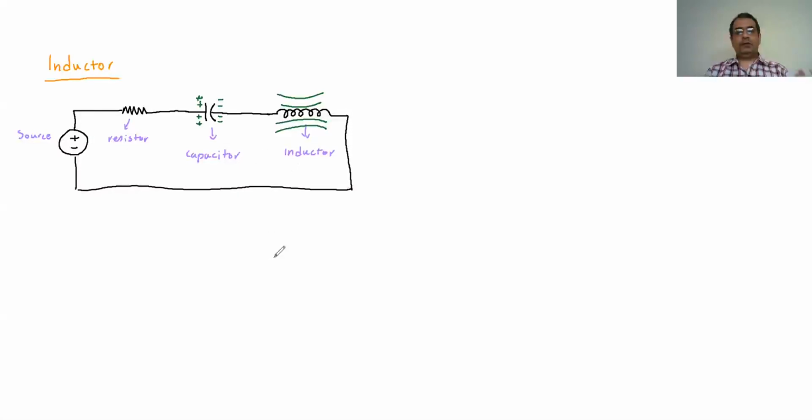So remember that whenever you work with the elements in a circuit, you may disconnect the source. You look at your circuit and see there's no battery connected, or it's not connected to any source of energy. But still, these two might hold the energy. So if you touch it, you're going to get shocked, because although they might not be connected to the source, they store the energy inside them, and the shock is going to be very high, because some of them store a large amount of energy and can release it very quickly.